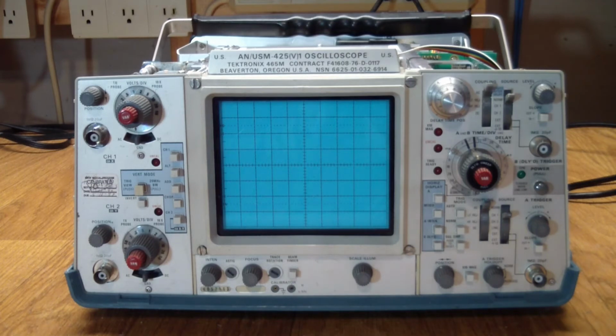It sits at like a 30-degree angle to the board. I had to try a couple of times making sure not to burn anything around it. But finally it got in there, and I yanked on it with a pair of pliers on the pin I had soldered back, and it seemed solid. Then I inserted the connector back in the pin and set everything upright.